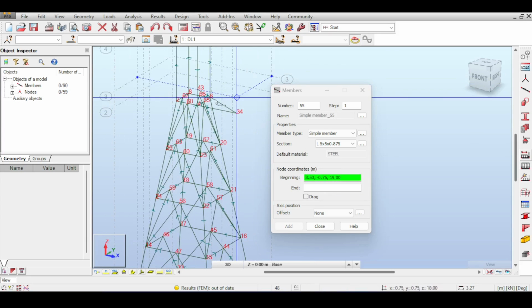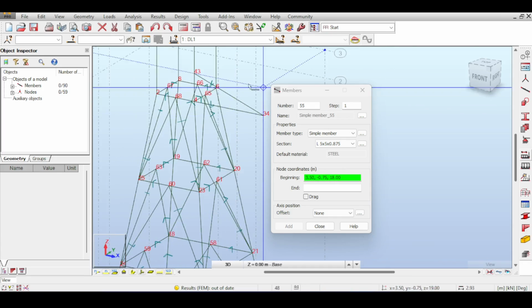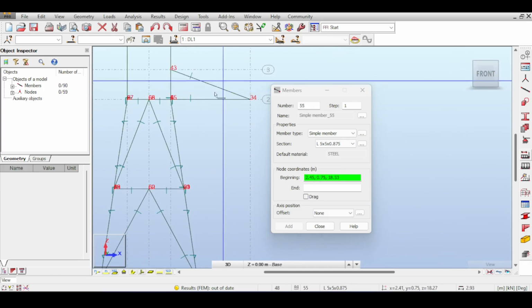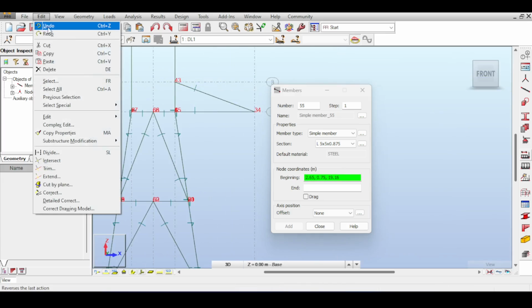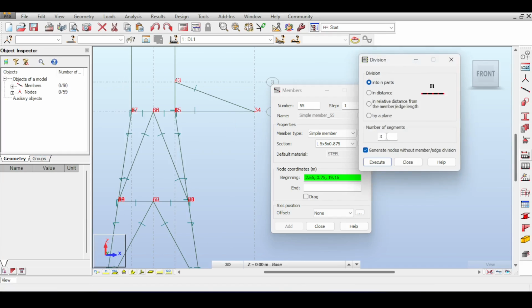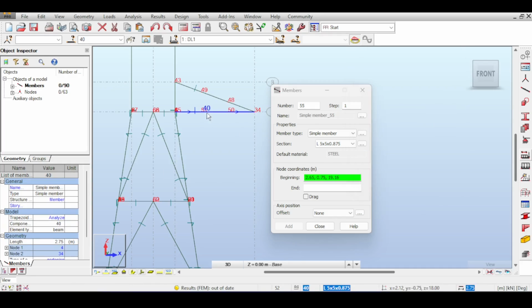And I'm gonna copy this, by the way, so this time I'm not gonna draw everything. And now you have some bracings and some disconnect cuts, so we're gonna split this into 3 pieces. So let's do that. I just go to edit, divide, and split this into 3 pieces without division. I'm gonna split this into 3 pieces and this into 3 pieces. And now I'm gonna just make my truss. Of course you can assume any truss. I'm just gonna assume this little thing.